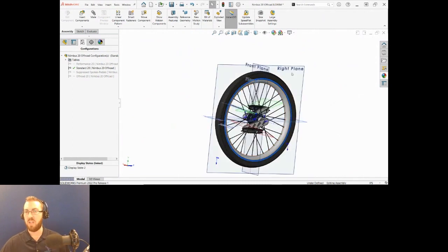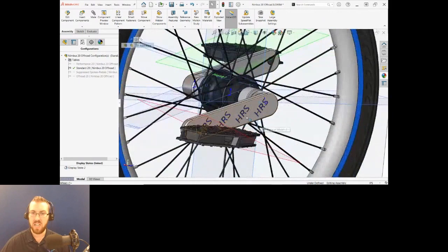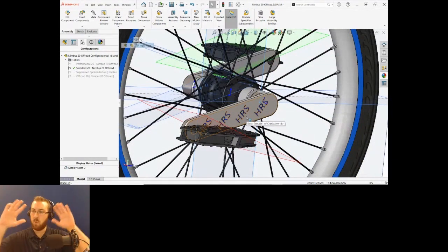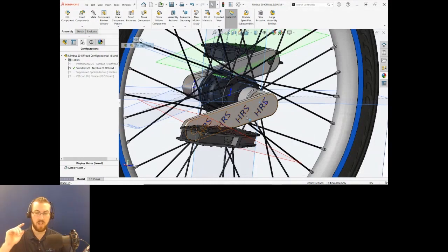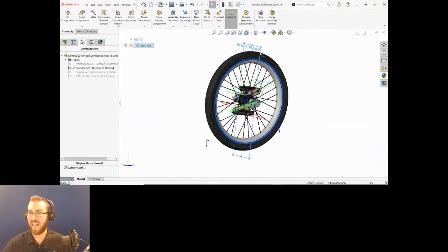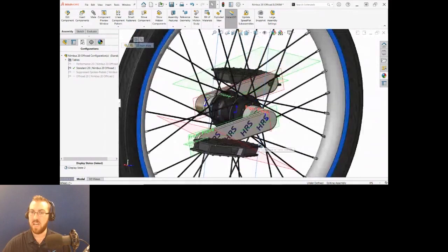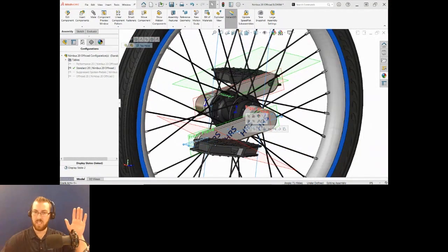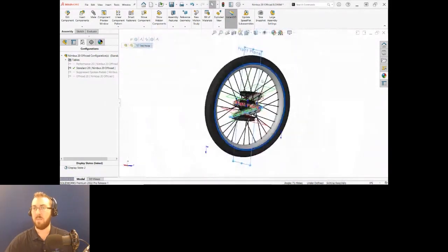If you're using the Q key to make a plane selection, let's say select the front plane, and then I want to select another plane from a different component. So this was a plane from the wheel. Let's say I want to select a plane from the crank now. What I would do is take my hands off the keyboard, not holding control. Now I'm going to just press Q while hovering over that crank to show those planes. Now is when you would hold control, because that front plane that I had selected for the wheel is still selected. Now you hold control and select the other plane that you want. And then you can release again, and both of those would then be selected.